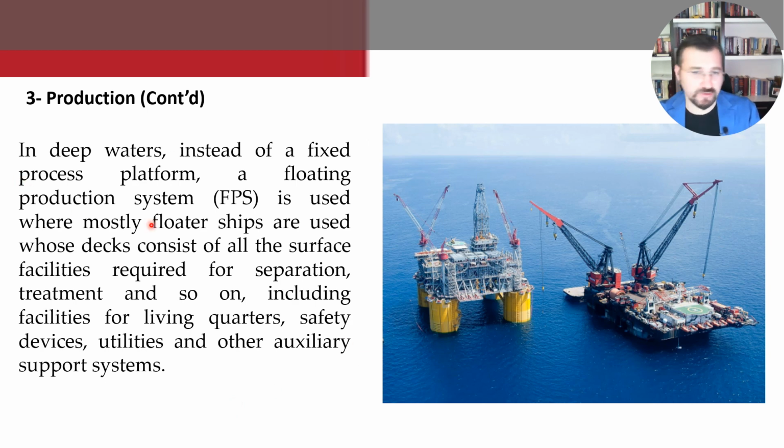Like floating production system, FPS, and then when you add storage and offloading, FPSO: production, storage, and offloading. These FPSs receive the well fluid from the subsea wells through different production risers, which are flexible pipes of different configurations and sizes. For offloading, other risers are used, which are commonly termed export risers. An elaborate discussion on this will be made subsequently; we will cover all of these in the next weeks.